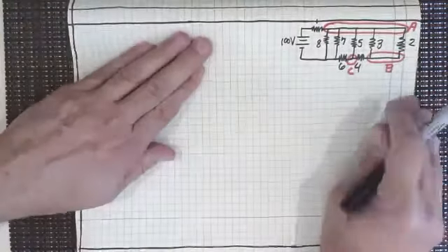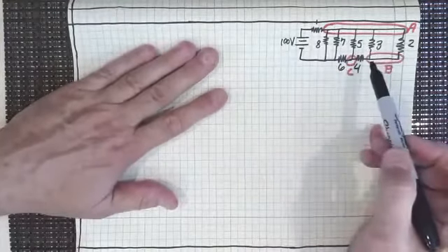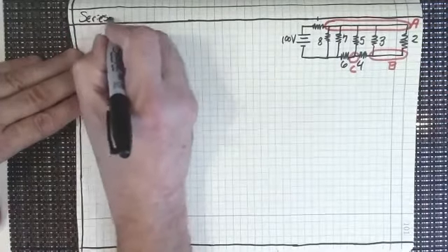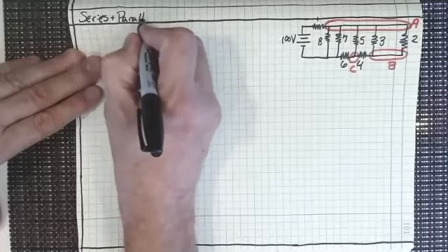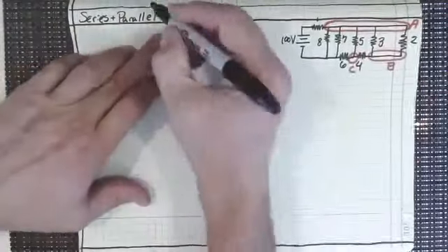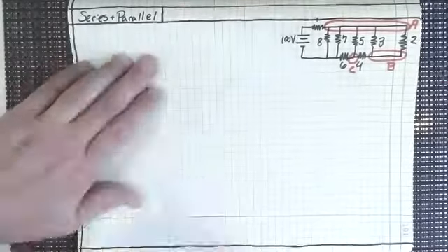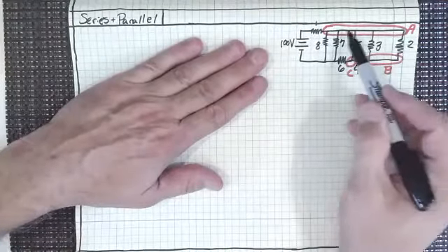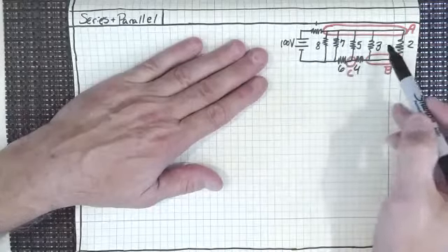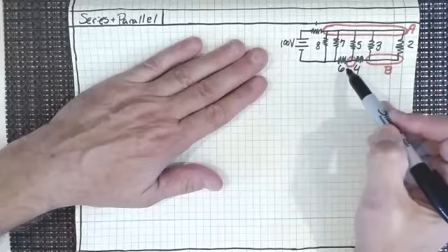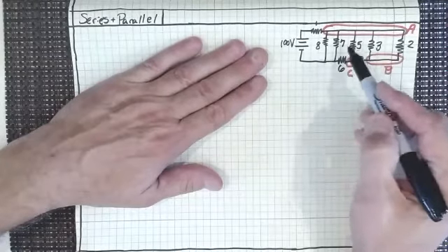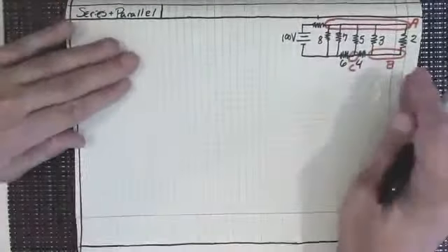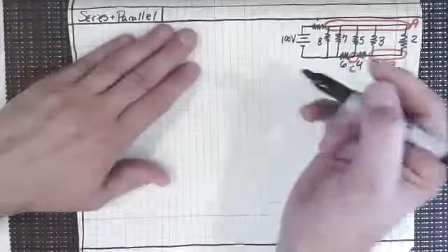And we're really looking at something here that still is a series parallel combination. So I'm going to put that up here: series parallel combination. So that's what we're looking at, and we've simplified it down to this point. Now we're going to use the Kirchhoff's current and voltage laws that we've seen before, and the simplification of the various series and parallel capacitors to further simplify this circuit, so that we can figure out at any of the individual nodes that we have here what the voltages are. And so that's what we want to look at.